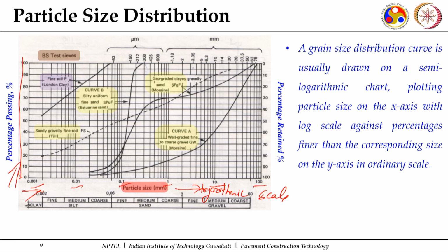Now, here what important thing you can see, when I did this gradation on different samples, maybe soil or many others, this gradation has to be done, or the sieve size distribution, whether it is soil or any granular material, in the same fashion. The only thing which will vary will be the sieve sizes which you will be using for granular materials, and the ones which you are going to use when you are looking at soils, because the particle sizes which are present will vary in different materials. Now, you can arrive at various pieces of information through these size distribution curves.